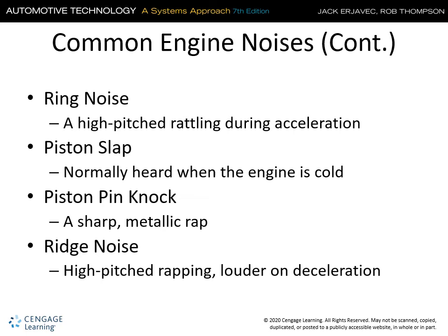Ring noise is high-pitched rattling. Piston slap is when the engine is cold and it hasn't gone to fully round and made it to temperature yet. That takes a moment. Pin knock is a hard metallic knock, and ridge noise is a rapping, louder on deceleration. That's the piston and the piston ring hitting the carbon ridge. That's at top dead center for the compression ring.